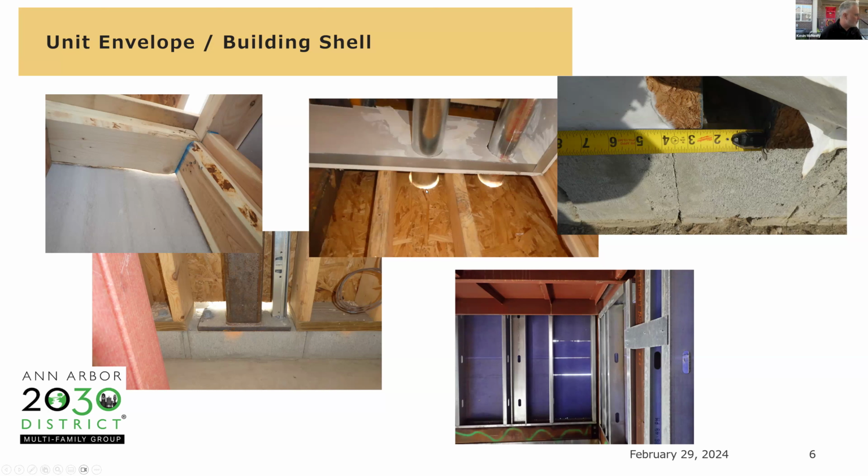I'll get into materials and products that we can use later on. And again, we need to not only seal the shell of the building, the exterior walls, but we also need to seal the interior walls. So here's a steel framed building where we have air leakage in the sheathing, and we're going to have air movement that comes through all the holes in the studs here. So it's going to be able to move through interior walls, and wood framing is the same. It's just not as obvious in wood framing.